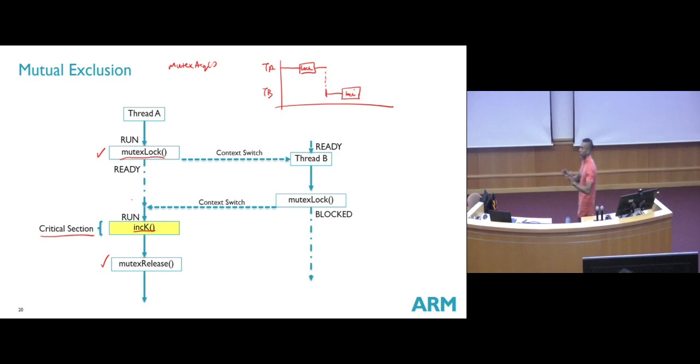So the OS will manage this for us, to ensure that only one person has access to the mutex at any point of time. Since task A already locked the mutex, and now task B is trying to lock the mutex, it cannot lock it. So what will it do? It will go to a block state. This ensures that task B cannot continue and take the K variable.